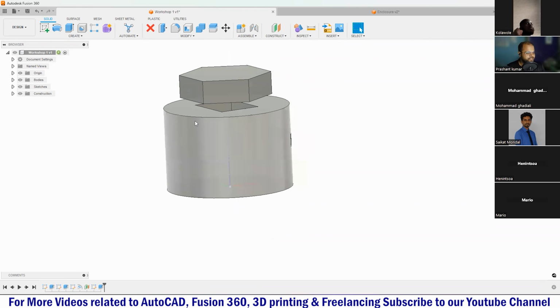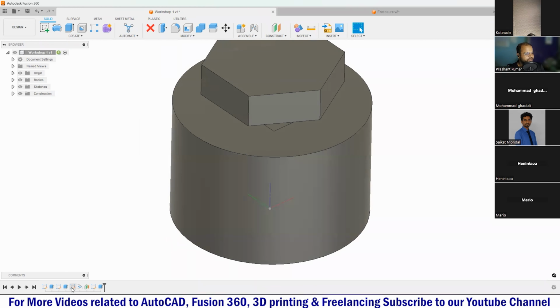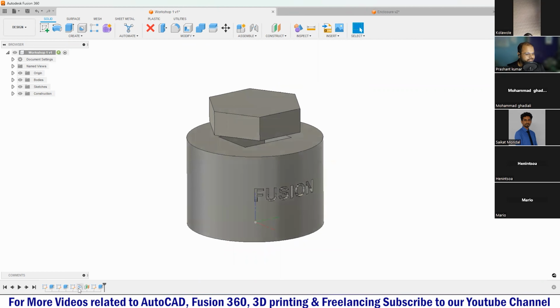So it's really easy. Now let's move on to our next thing that we had planned for this workshop today. Here you can see we had just created the 3D model, and you can update your 3D models at any time. For example, if you're not happy with the text height, I mean the text size, you can just go to the operation that you had used to create your sketch. For example, I had used this sketch tool to create this text. So I will just go to that option.